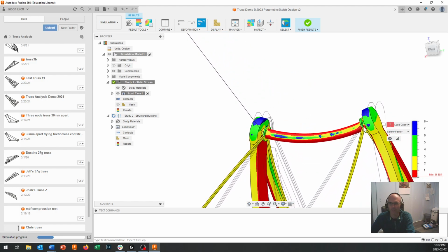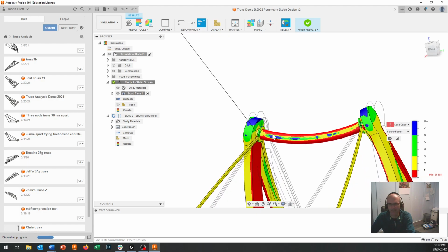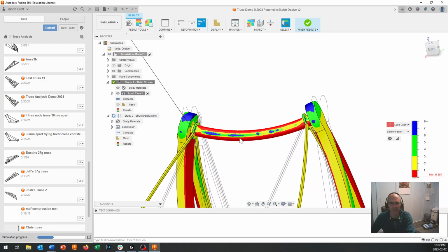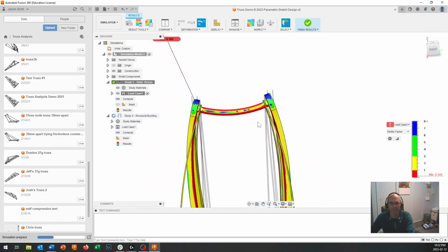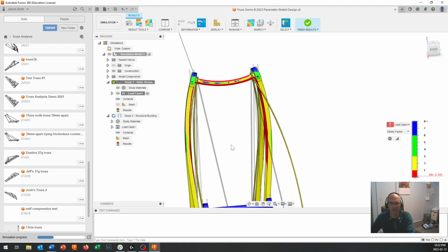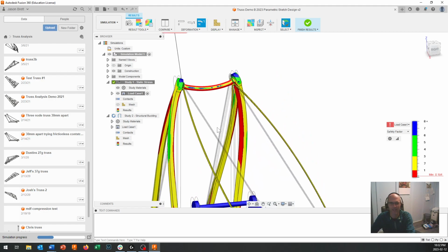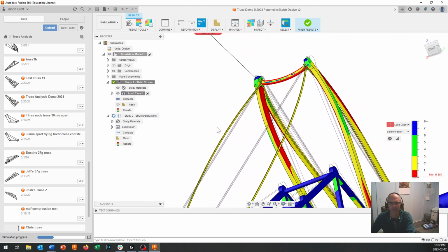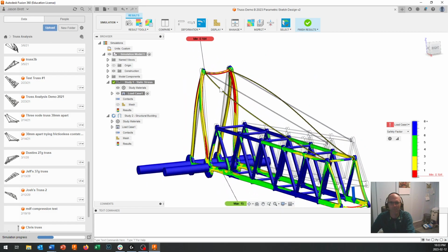And we can also increase the size of this node and put a 3/8 inch dowel right across there, which would really stiffen up that top. And I think that would help a lot because you can see if that's pulling down that hard that way and it's causing that to bend out already, this is just the static stress. It's not the structural buckling study. And that part worries me.